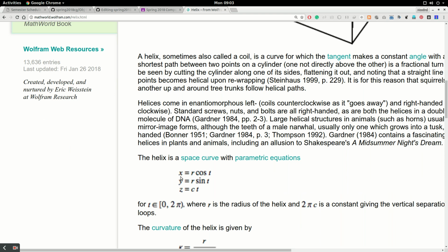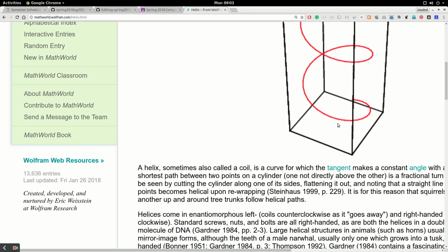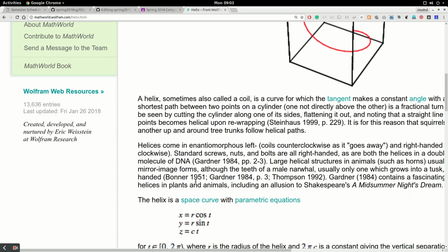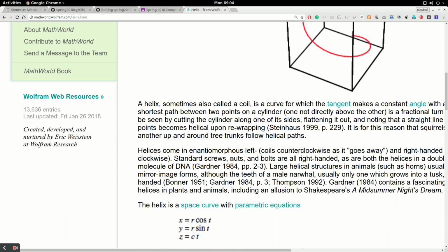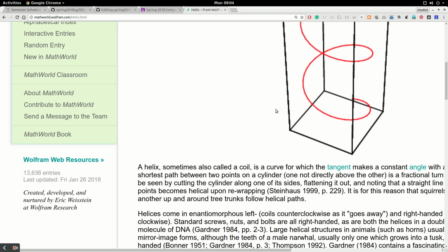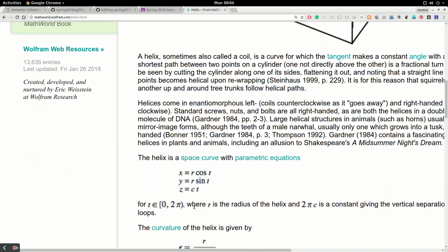So this thing is a parametric curve. As you keep on changing t, which can be the angle, you can generate the coordinates for x and y, and also for z, where c is another parameter that would define the springiness. If you have a low value for c, then it's going to be shrunk down. If you have a high value, then the spring will be really stretched. So you can take these things as parameters from the user: give me the value for r, give me the value for c, and based on that I can generate a helix.